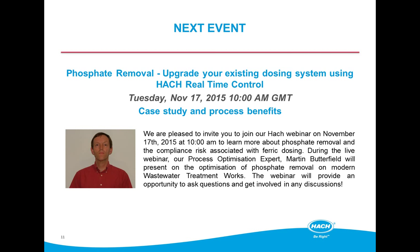Because that leads to another question that somebody's asked, which is, can you tell us about the maintenance requirements? So I think you've just maybe touched on that, but the maintenance requirements if you have a wet chemistry analyzer will be quite different to those if you had an ion selective electrode. Well, basically you've got a service visit every three months, which essentially is to replace chemical reagents and things like that.